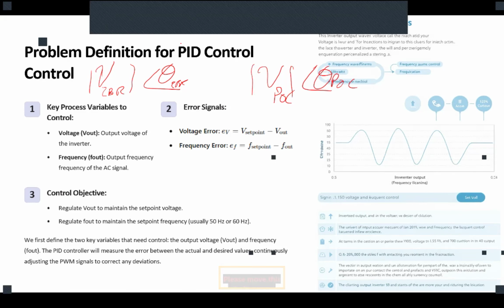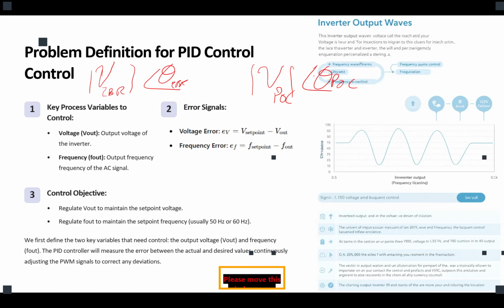Now the difference between theta POC and theta IBR, the two phases, at a given time. This is a time function, so frequency also defines that theta. So this is omega t plus theta naught. Do not consider that phase as a constant number. It's varying through time. So the difference between the two thetas defines how much power you inject or consume through your connection.